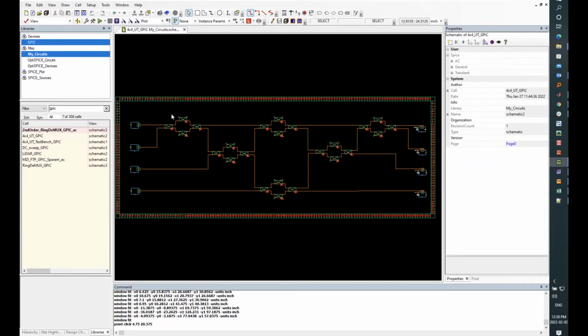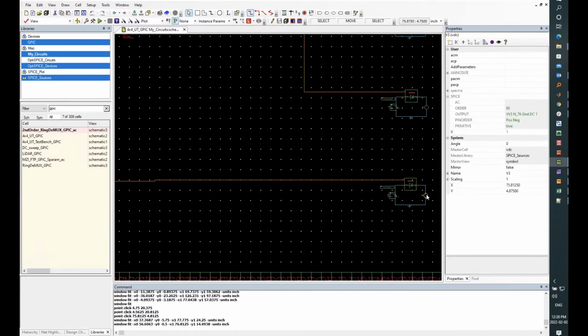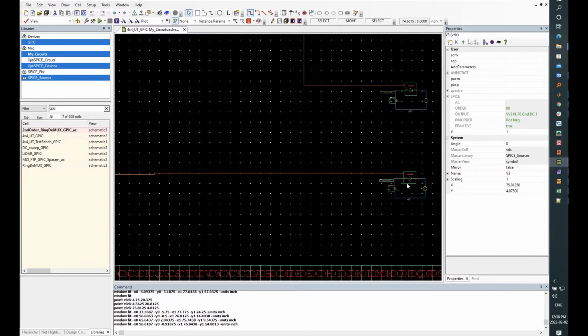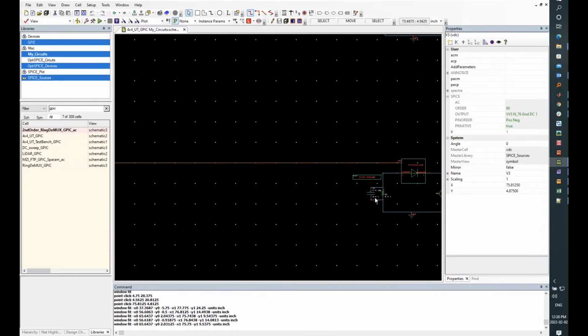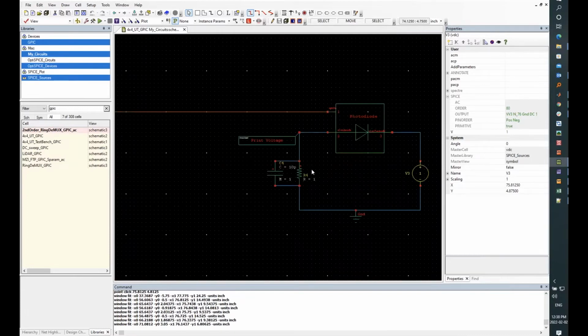So the way it works is, on the left-hand side, there are 4 different lasers sending in 4 different channels. So this is channel 1, and this channel will be obtained here in the output 4. To measure the outputs, we are using photodiodes, and we have a voltage source to drive the photodiode, and there's a resistor to measure the voltage.